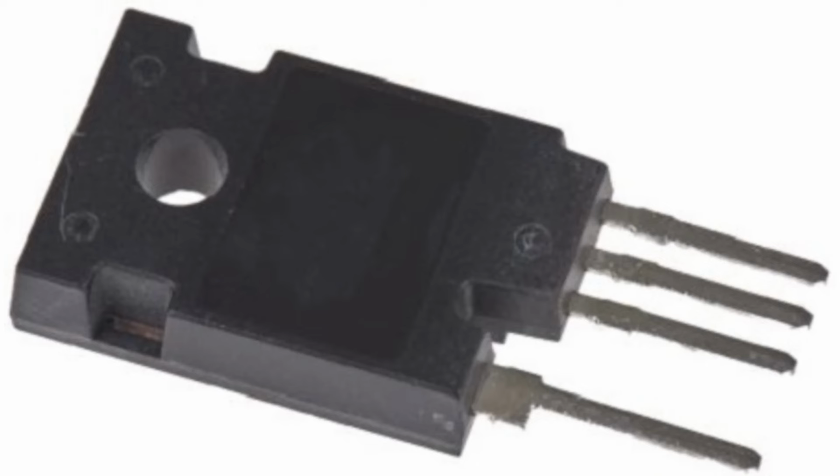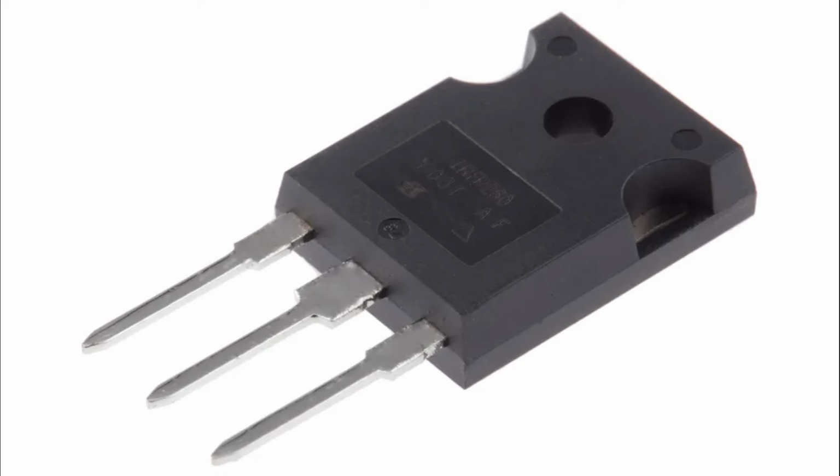3. Electrical characteristics. On-resistance, R_DS(on): when the MOSFET is in the on state, it has a low on-resistance, allowing current to flow with minimal voltage drop and power loss. The on-resistance is influenced by the MOSFET's design and materials. Drain current, I_D: the current flowing from the drain to the source when the MOSFET is on. It depends on the voltage across the drain-source terminals, V_DS, and the gate voltage, V_GS.